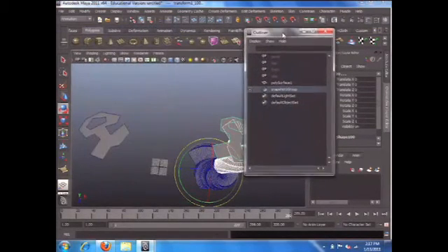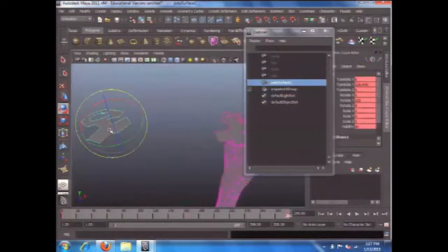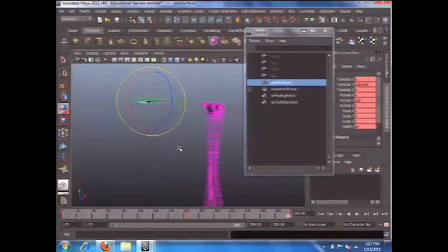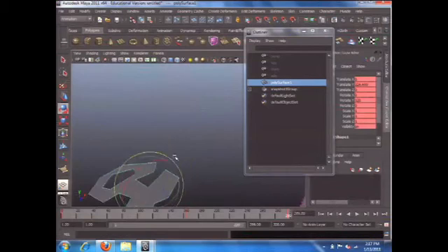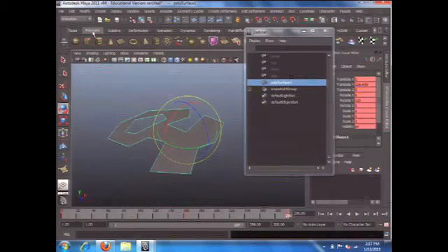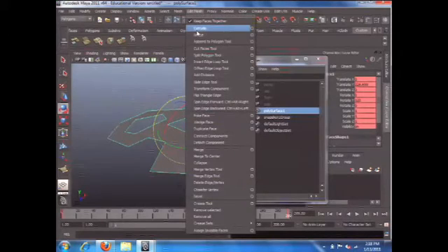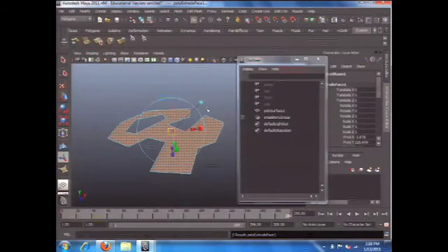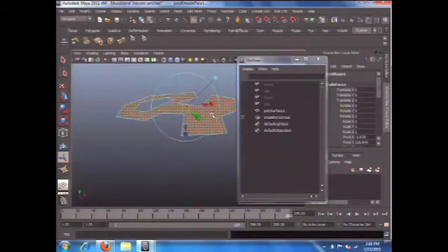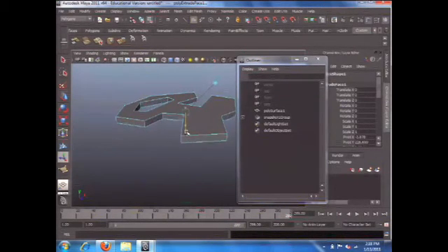And here's something even better. If I select the original object, I can make some more manipulation. Let's see, I want to make this guy have a depth. So I'm going back to my polygon menu, or I can go to my custom menu. Here's the tool I made a shortcut for last time: extrude the selected components. Remember that? You can also go back to the menu: polygon, extrude, the same thing. So if I extrude this guy, just drag this blue arrowhead a little bit. So I create a depth.